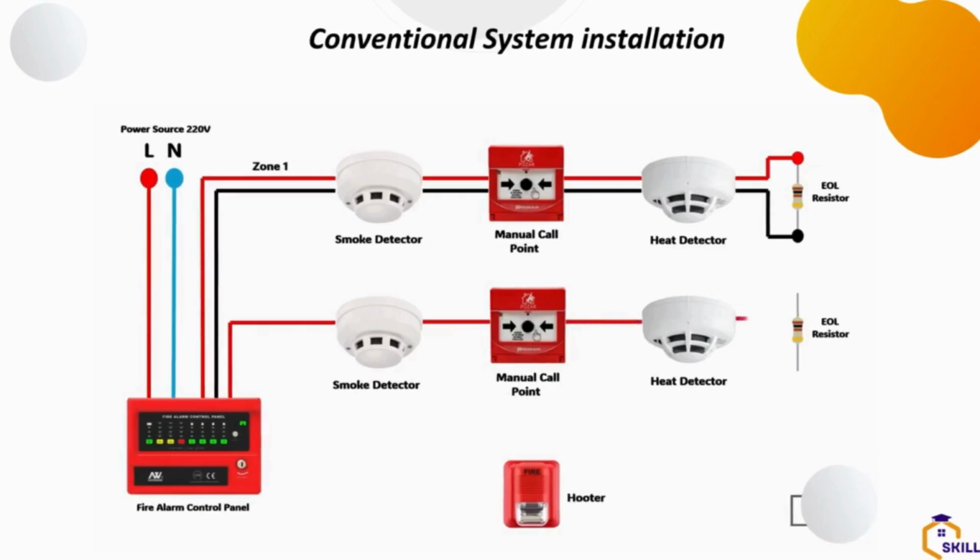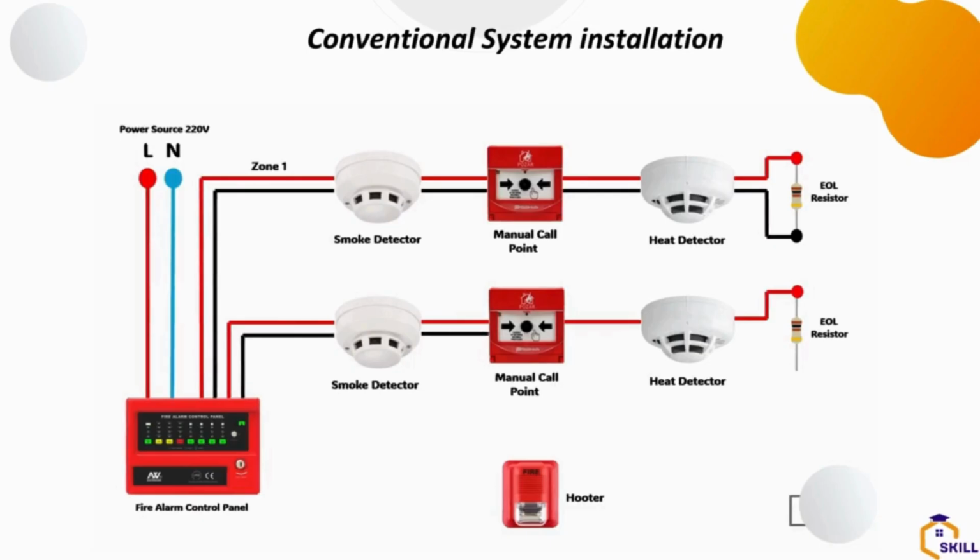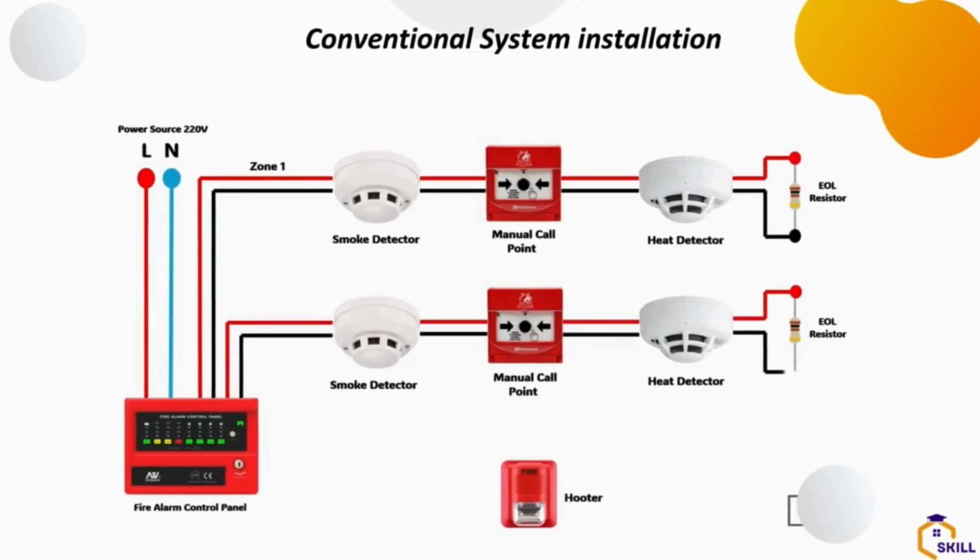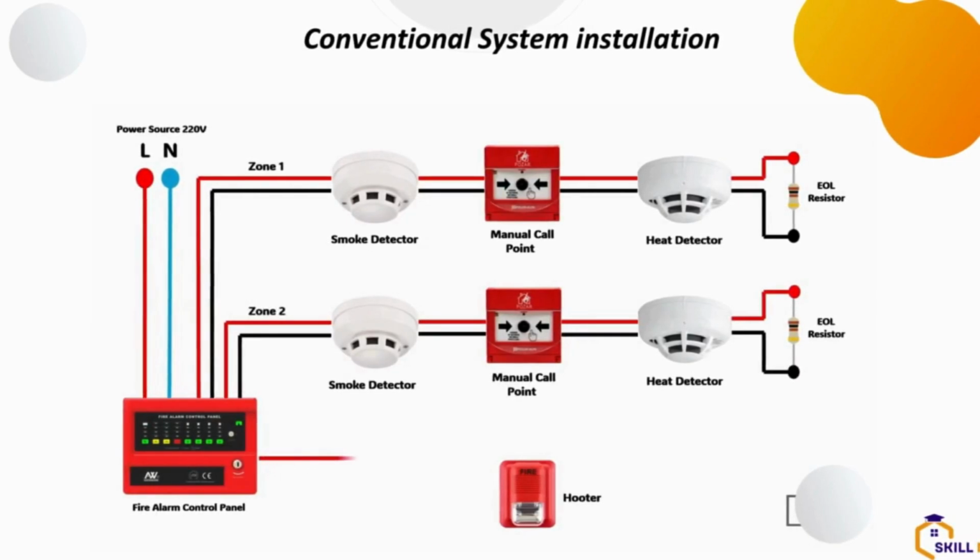This is just basically what you are doing. So the pipe has to link from the smoke detector to the manual call point. There's a link. So when you're running the cable, you drop for the smoke detector, you tie the cable. That's how we usually do it. You tie the cable there, you go to the next point, you tie it, till you get to the last point and get your system ready for mounting of devices. You now start mounting one after the other.